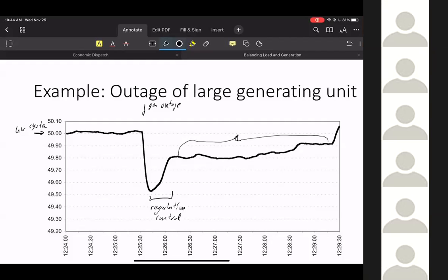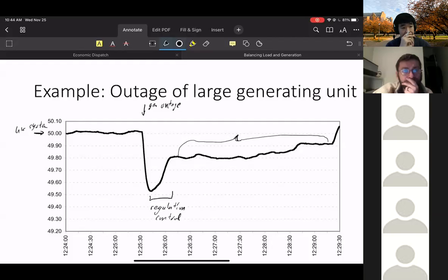My guess would be that the energy stored in the inertia of the generators is causing the slight increase, and then the big recovery is when they actually have the time to open their gates or whatever their type of prime mover controller is. You know, that delay that you were talking about before finally kicks in and begins to actually increase the speed that they're spinning at again. Close. So some phenomenon close to that.